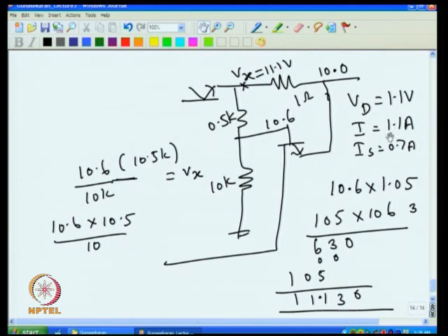But actually the basic principle of working is like this: the voltage that is there across this resistor, under normal working condition, because in normal working condition you have 10 volt and that 10 volt also will be reflected here. That 10 volt is divided between these two resistors. So there is some voltage drop across this under normal working condition, that is working as a reverse bias for this.